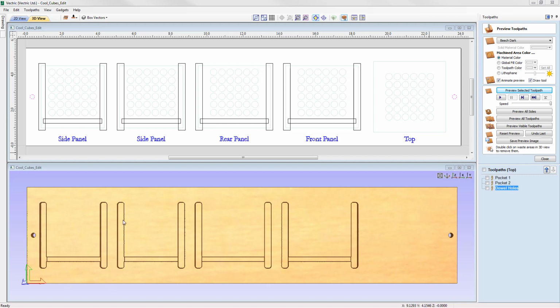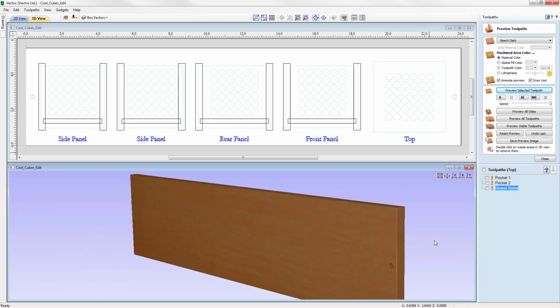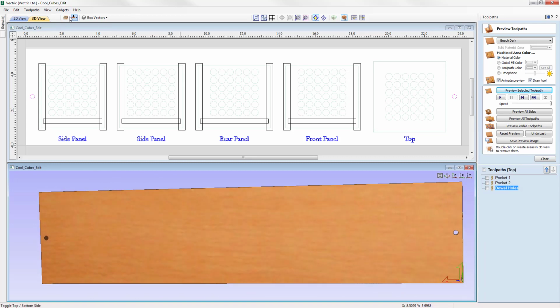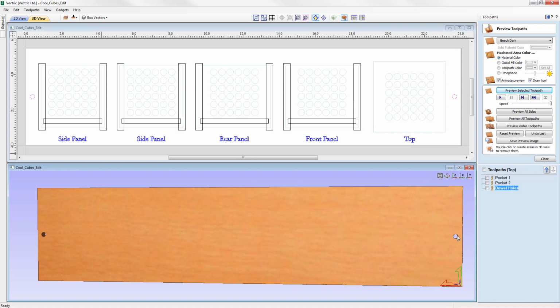And then we'd take our material that we've already cut into and flip that over, ensuring that we're flipping that over in the same direction that we've set in the software. So in this example, we're going horizontally here, and then we'd secure that in place to the dowel holes, and that way we know that our XY coordinates are going to be aligned with each other on the top and the bottom sides.